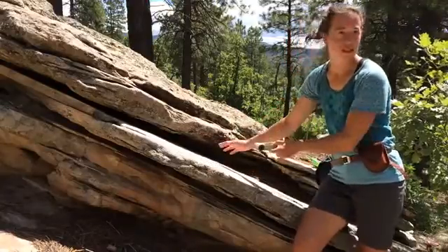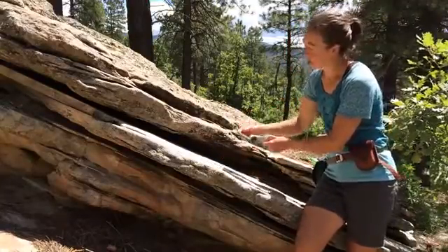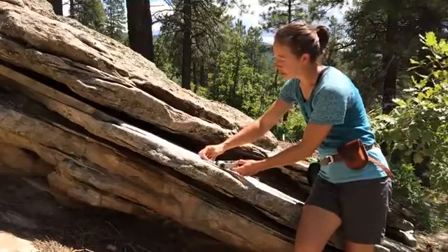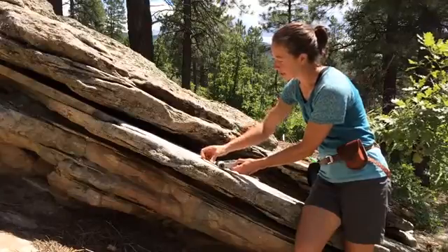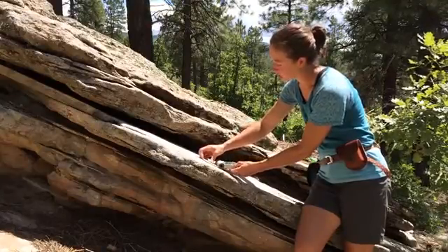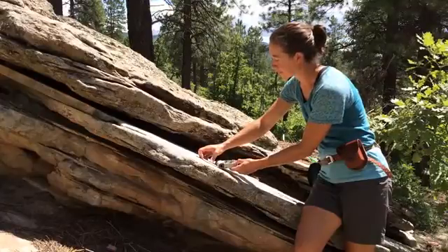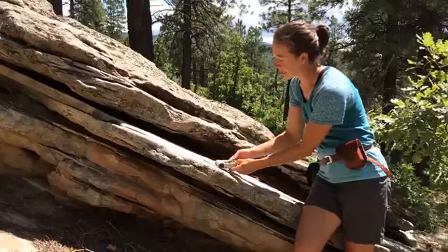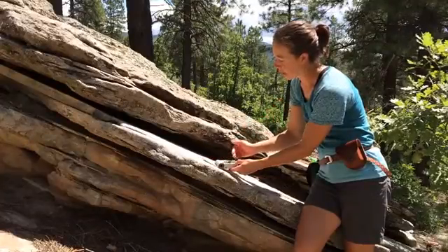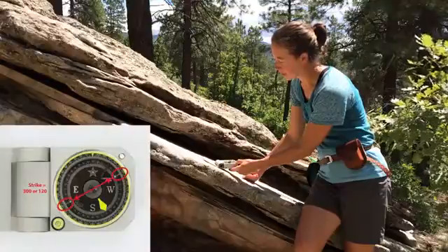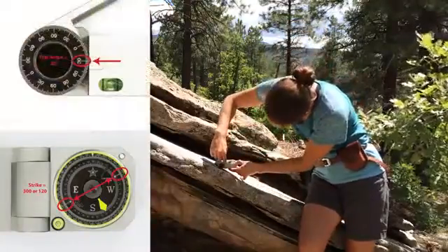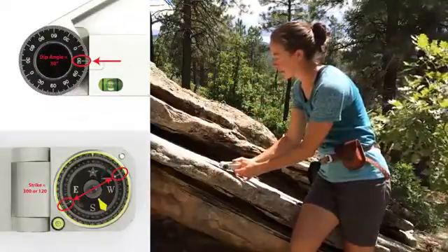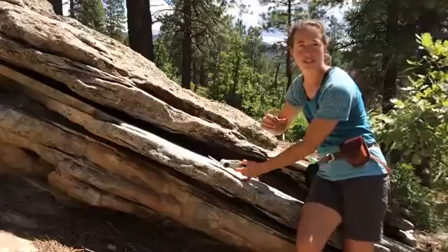So let's review this basic strike and dip measurement. The first step is to place the lid against the plane. Next, level the compass face by swiveling the lid and also rotating around the major axis. When the compass is level, press and release the needle button. Read strike off of either end of the magnetic needle. Read dip off of the hinge dial, in this case where it meets the top of the dip indicator, and then take note of dip direction.